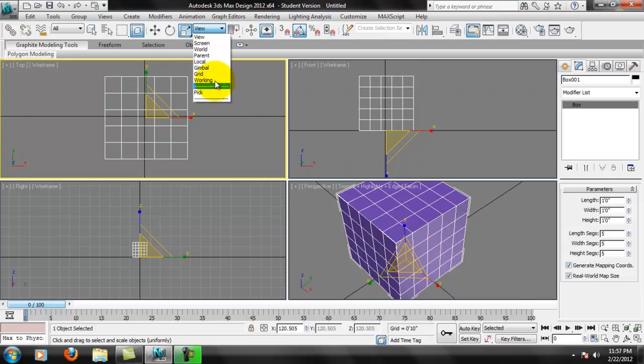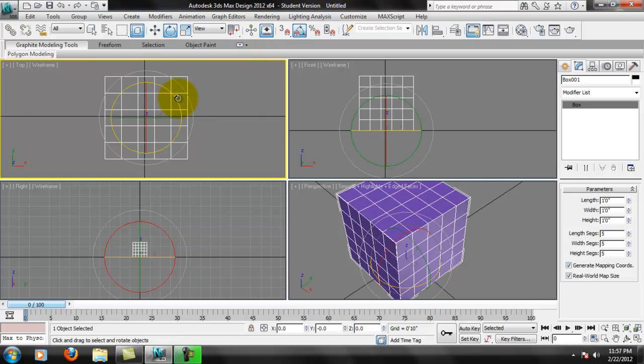The reference coordinate system, once we start getting into different grids and more complex things, we can adjust, similar to AutoCAD again, we can adjust our view. Keeping that on view 9 times out of 10 will be fine. But if we need to adjust the coordinate system, this is where we'll come to in the future. Pivot point center has to do with rotation and multiple objects. So, for example, if I rotate this object here, I rotate it on the center of that object.